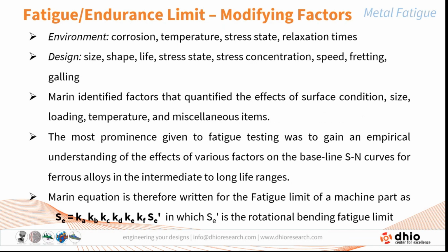Not only that, even the environment has an effect, through corrosion and chemical effects, or if there is a variation in temperature, the behavior of the material is going to be totally different. And the stress states, conditions, and the relaxation time for stress relaxation and other things, as in the case of creep, where a constant stress acting for a long duration of time may also cause failure in the component.